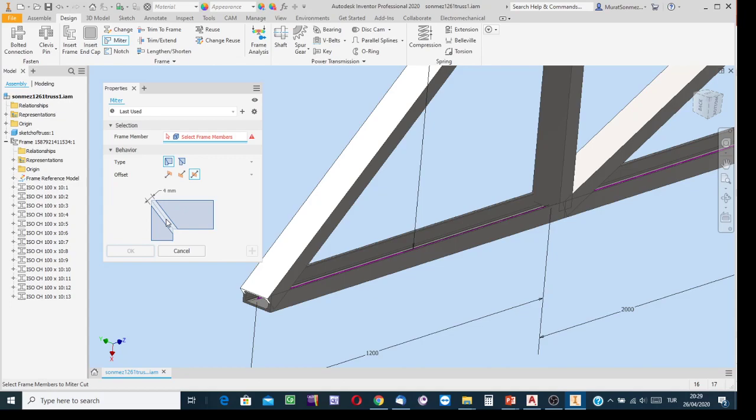Okay? But if you say that, no, well, I'm going to connect the members not directly to each other, but using gusset plates connect them to each other, then yes, well, this space may be even 0. I haven't decided right now. Well, here I'm going to say that, okay, there should be between them how many? Make a click here, say 5 millimeters. Empty space. I decided. And then the rest. Indicate the members. Order is not so important. First this and then the other, or vice versa.